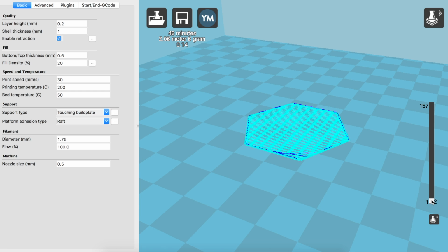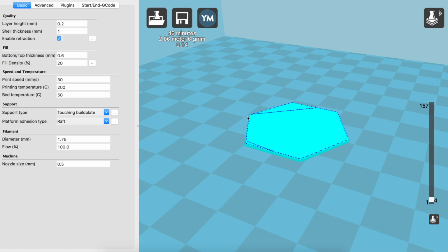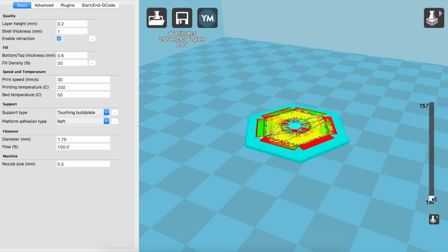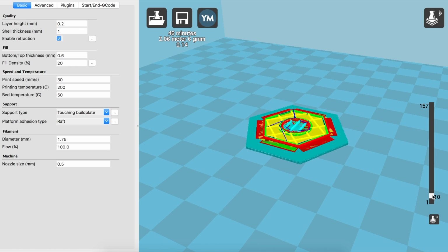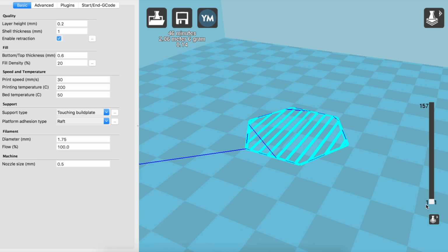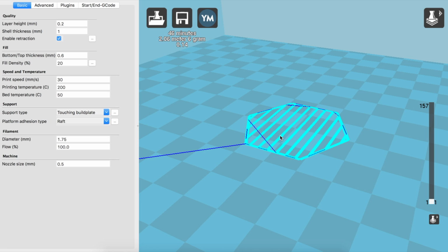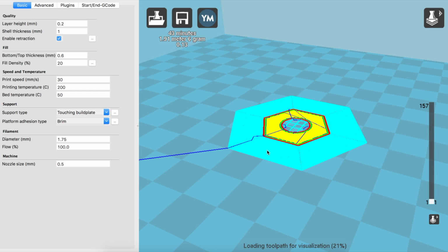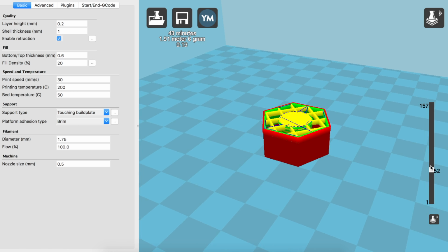But in my experience, having a good flat, solid print bed and different adhesion methods that we'll talk about later, I have never needed a raft, and actually the couple times that I've used them, they've been detrimental. So they take a little bit more material and they take more time, and I really don't like them. But for the use, let's just use a brim so that you guys can see how that works.